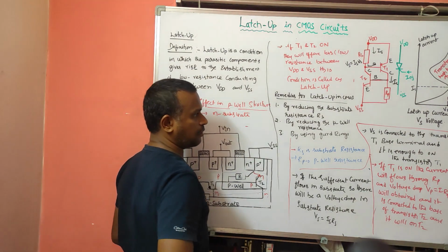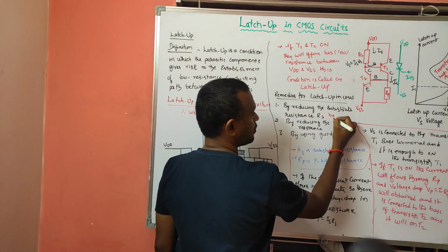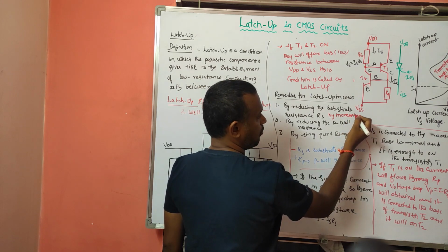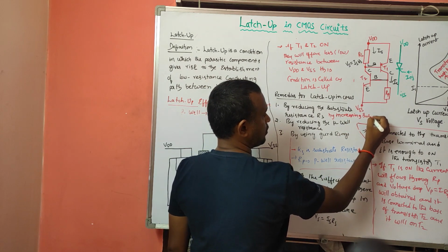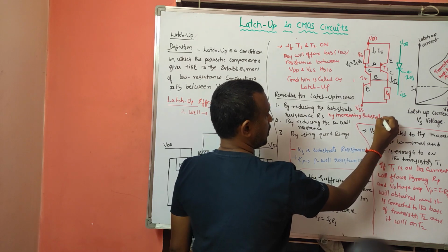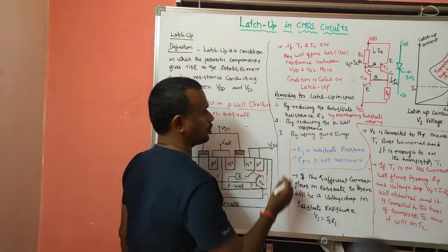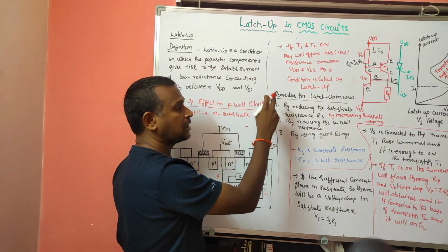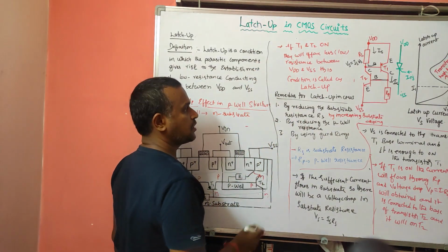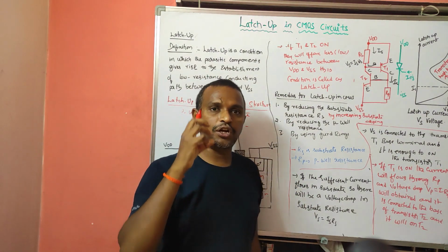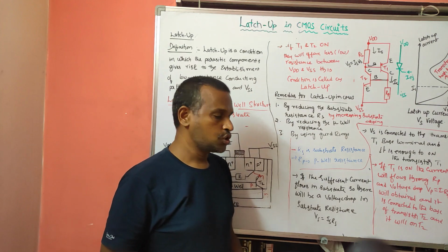So that is a very important point, increasing the substrate doping. This is one method to avoid the latch-up condition in CMOS. And how does it work?